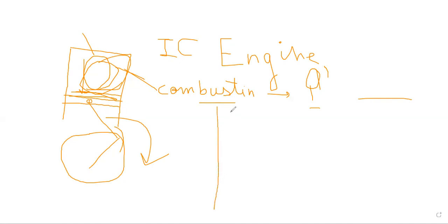So I will model air as a closed system that is undergoing several processes. And if we want to do the analysis of what is happening, we can divide it into mainly four steps. First, for example, the piston, the air within the cylinder will be compressed. If you want to present this on a PV diagram, I should identify a first state, point one.